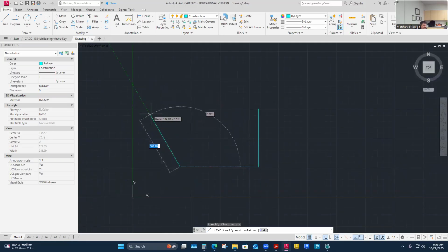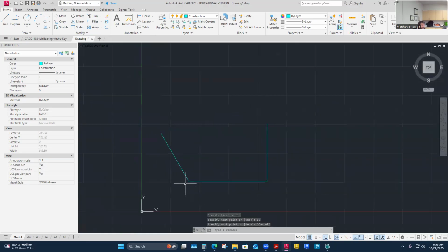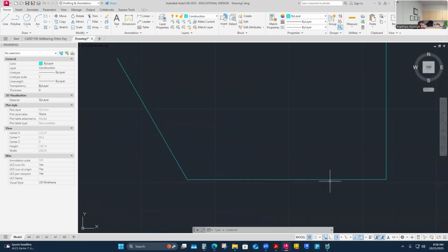Up some height here. This is pretty easy in CAD to draw because I can add that height while polar aligning to that 120 degrees. So I could tab over and make it lock in at 120 and then tab back, because you could pull that slightly, right? So if I lock that in at 120, it's a little safer. And then 95 is how long this side of that is. So it ends up looking something like about that. Yeah, 135. That's my 95 plus 40.